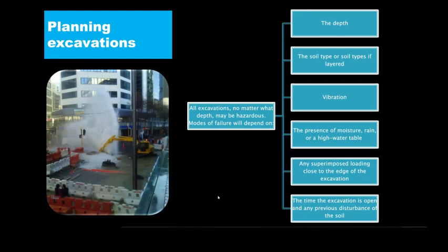There's less chance of you being injured, but quite often you've got to bend down to the ground level to fit the pipe or join it. So that does leave you quite exposed if even a moderately deep trench like a metre deep collapses. You could still potentially get injured or stuck under there.